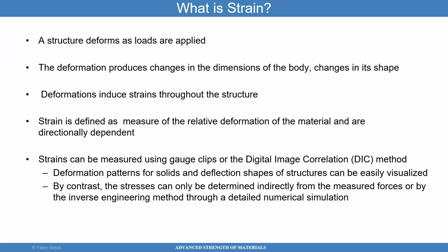That technique is used with quite a bit of high confidence to take 3D measurements of deformations and displacements, and can be used in combination with strain gauges. It is a non-contact optical technique that can tell you quite a bit about the structure. That's why it has become modern, and I have been able to use it in a lot of my work in aerospace design. Deformations and patterns can be visualized with DIC.